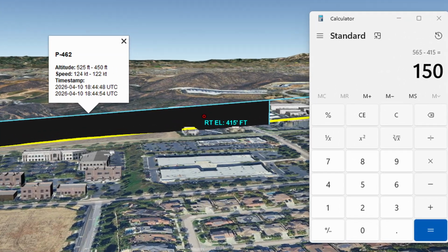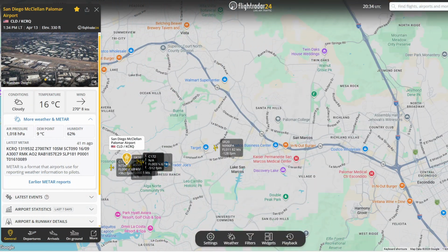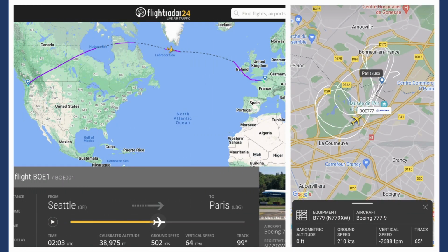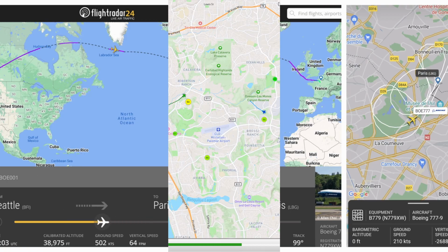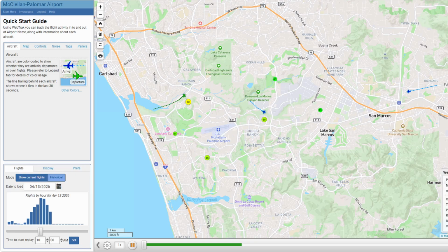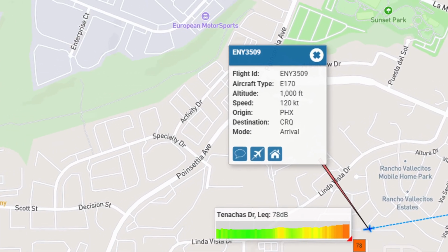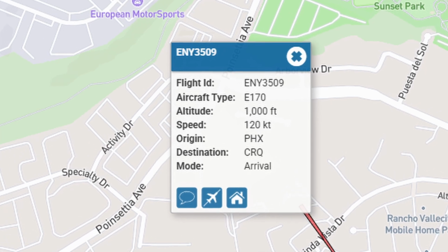Historical flight data also depends on where you pull it from. FlightRadar24 uses a mix of ADS-B and official FAA radar history. Raw ADS-B can be very accurate, but after processing you may see smoothing, gap filling and other make-it-look-nice adjustments. WebTrack is widely used for noise monitoring and it's the airport's official complaint site, but the altitude can look wildly off sometimes. It may be displaying altitude differently, potentially closer to above ground, which gets complicated fast when the terrain isn't flat.